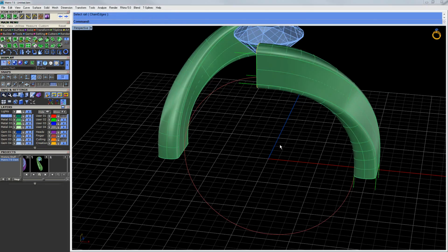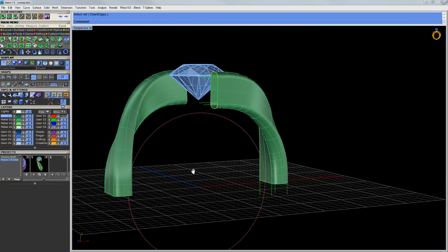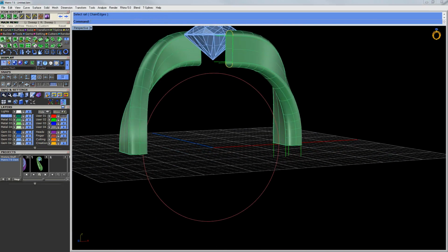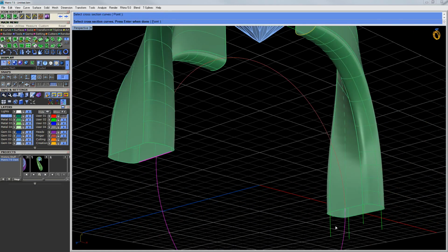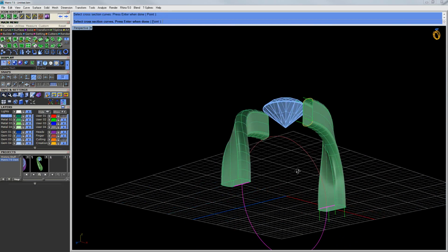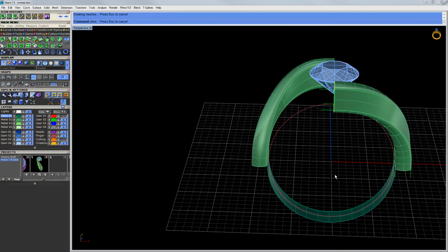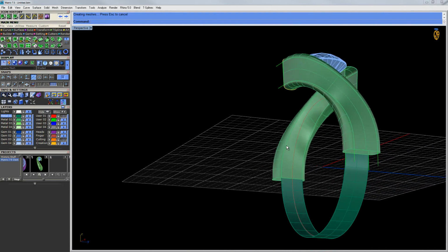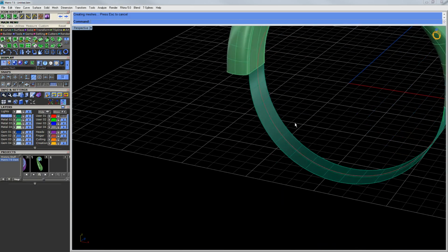Alright, so we'll go ahead and use sweep 1 to start finishing off the bottom here to get our start. So we'll choose sweep 1, and we'll pick our surface edges. That way I can use Rhino's sweep, press enter. And you can see we get that nice first portion of the bottom there. And I can do the same thing with the outside of it there.